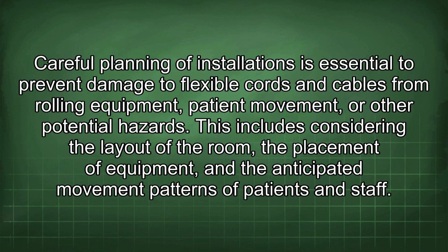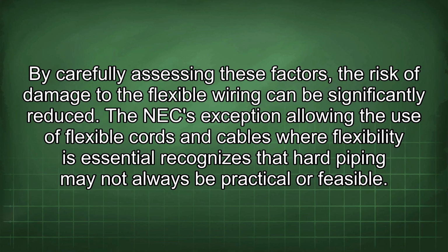Careful planning of installations is essential to prevent damage to flexible cords and cables from rolling equipment, patient movement, or other potential hazards. This includes considering the layout of the room, the placement of equipment, and the anticipated movement patterns of patients and staff. By carefully assessing these factors, the risk of damage to the flexible wiring can be significantly reduced.